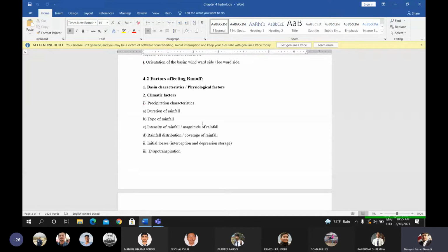That is, the top layer of the soil will be compacted by the rainwater, so the infiltration of water into the underground soil will be less, because the soil particles on the surface of the land are compacted by the rain droplets hitting them. The compacted upper layer does not allow much water to infiltrate, hence the chance of surface runoff will be high if there is a high intensity of rainfall.